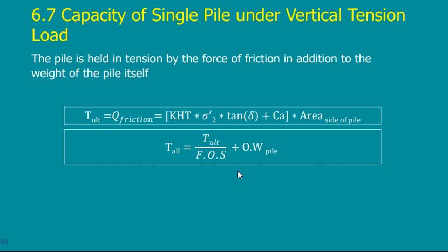That's all. So in this case, the only difference, if I tell you in any of these problems, calculate the compression and the tension load: for the compression, you will give me the previous numbers, but for the tension, you will exclude the portion of the end bearing, and you will take the friction only. You see, now we have many combinations.